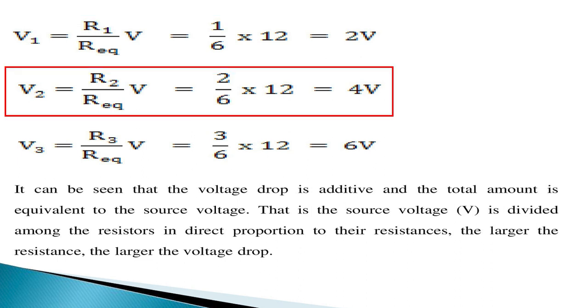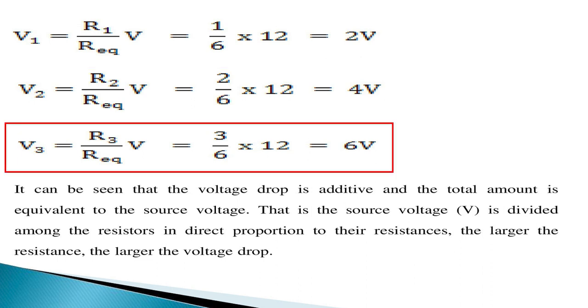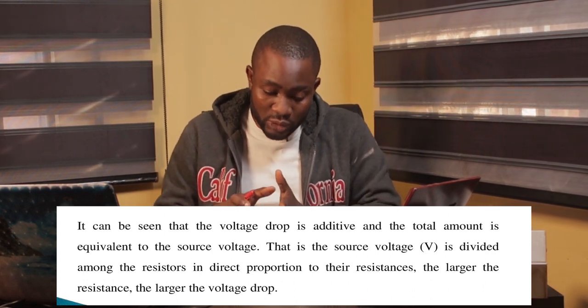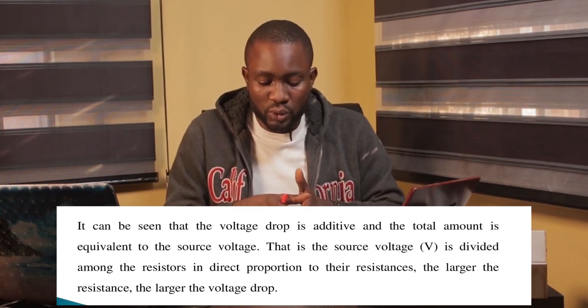Our V2, from equation 7 above, is R2 over R equivalent times V. Our R2 is 2 ohms. 2 divided by 6 times 12 gives us 4 volts. Our V3 from equation 7 is R3 over R equivalent times V. Our R3 is 3 ohms. 3 divided by 6 times 12 gives us 6 volts. So you can see that the voltage drops are additive: the total, which is equivalent to the source voltage, is equal to the voltage drops across the resistors.